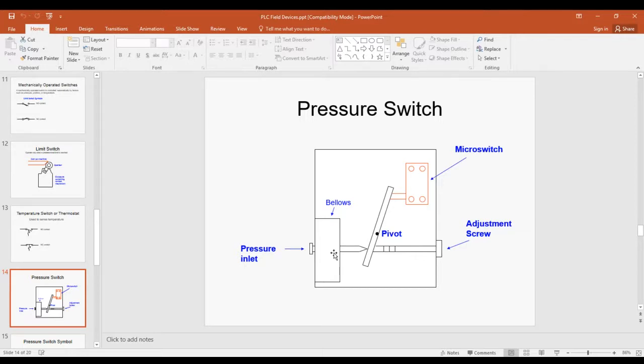So you can use those little piezo sensors as a pressure sensor. It's an actual solid crystal that if you squeeze it, you get a bit of voltage. We're probably talking microvolts, but then you can amplify that. That voltage is proportional to the amount of pressure on it, so you can use that for a pressure switch. They also use those in old watches made with crystals: they apply an electric current and the crystals vibrate so precisely they can keep time. So crystals would probably be how the sensor is done, and I'm sure there are other ways to do pressure sensors.